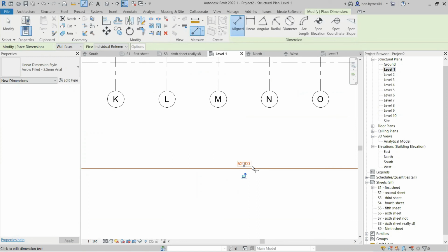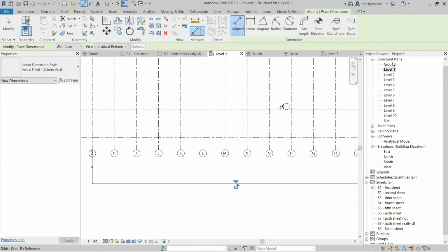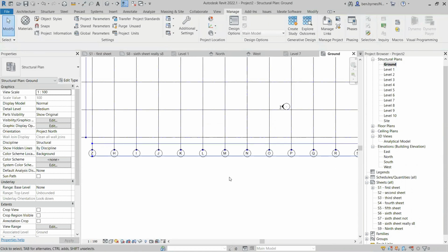That's one thing with Dynamo. When you're updating particularly geometry and stuff, it will override what you had in there before. There is a bake node. I believe it's not an out of the box one. I think it's in a package, and you can basically get that one. As we've seen, the dimensions will disappear. It did override that totally. So those dimensions have disappeared.